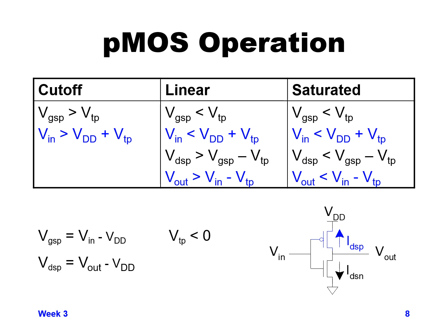than VDD plus a negative threshold voltage, Vn is close to VDD, it can be a little bit less than VDD, but not less than VDD by whatever the absolute value of that threshold voltage of your P device is. And if that's true, you're close to VDD, then you're going to be in cutoff region.